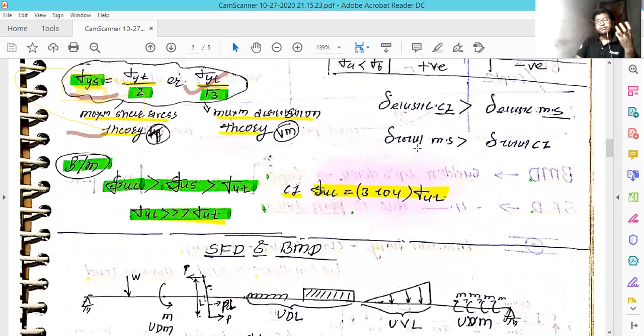But if you take the total deformation, the mild steel will be deformed in a very large manner compared to the cast iron. So, if it is asked within the elastic limit, the cast iron will be deformed by a greater amount compared to the mild steel. And if it is asked for the total amount of deformation, the mild steel is going to be deformed in a larger quantity compared to the cast iron.